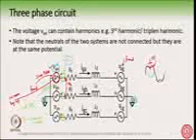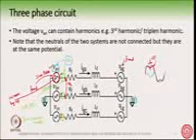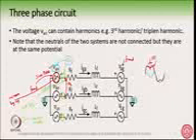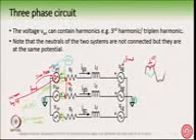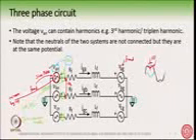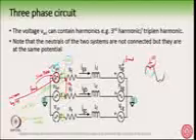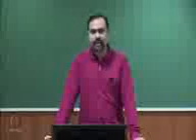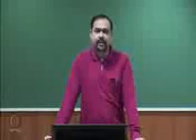This is important for us to understand, and you can have different types of common mode voltage. It is not necessary that you have a third or ninth. You can have different types of common mode voltages. But the benefit of this common mode voltage is that we try to get more fundamental VAN, VBN and VCN, as we had earlier discussed in one of the previous lectures.